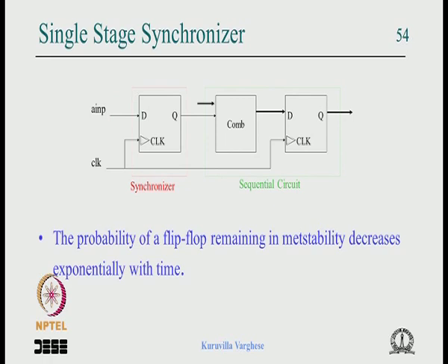So now the good news. This is a single stage synchronizer, this is a synchronizer, this is a sequential circuit. The good news is that the probability of a flip flop remaining in metastability decreases exponentially with time, okay. Mind you, read carefully: the probability of a flip flop remaining in metastability decreases exponentially with time.